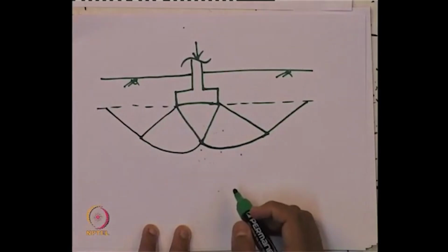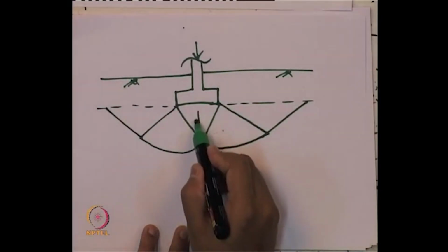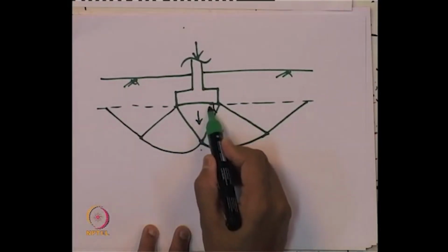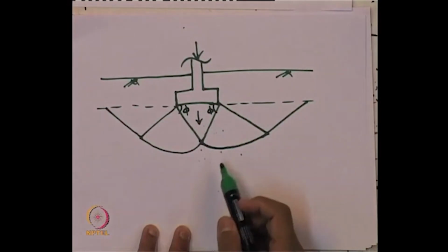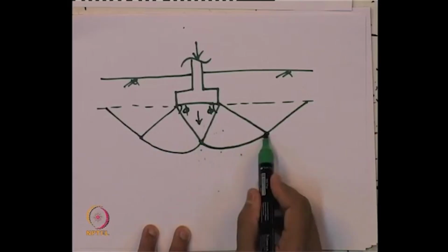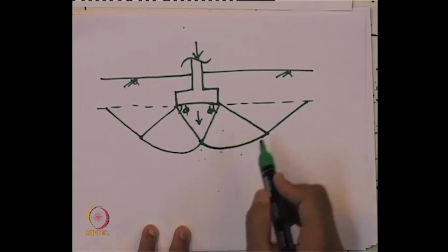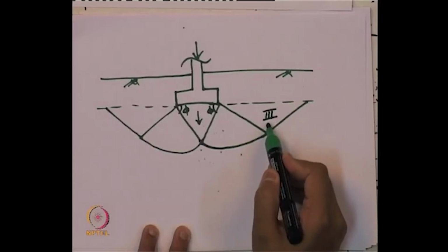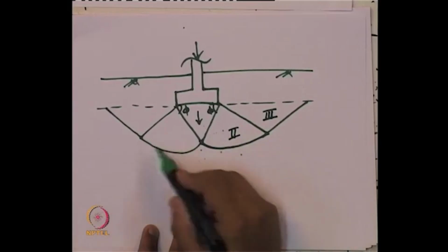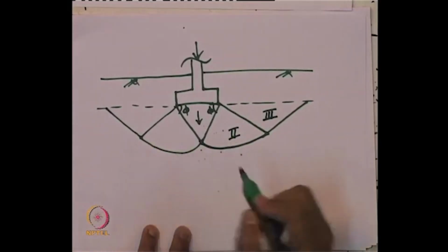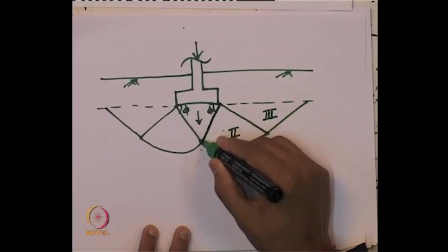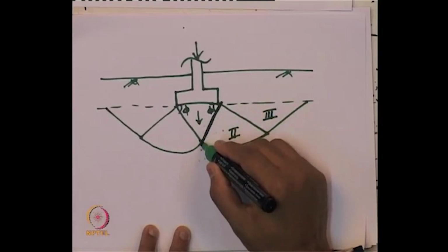So, this is Terzaghi's theory, which says we have one zone over here, and this angle is phi for the static case. This is zone 1, which is named the active zone. This is zone 2, which is the log spiral zone, and zone 3 is the Rankine passive zone. This is the log spiral zone, and it is asymmetrical under the static condition. Now, if we consider this line as an imaginary wall, what can we say?